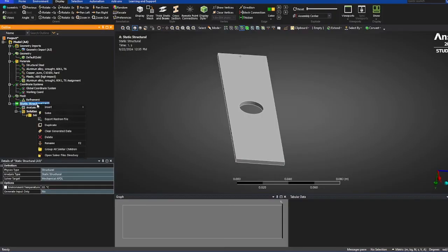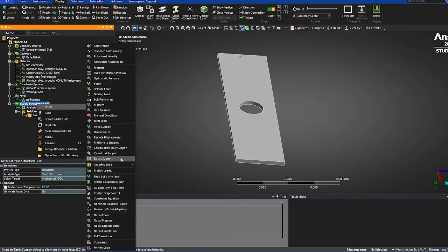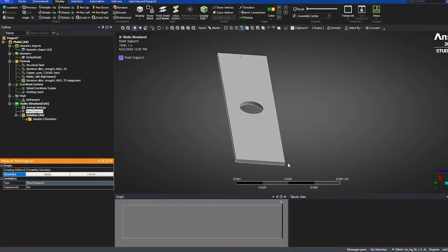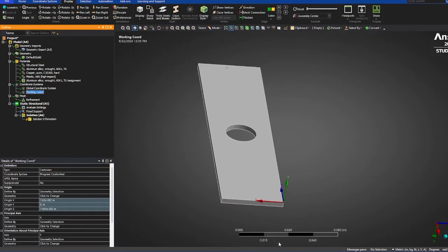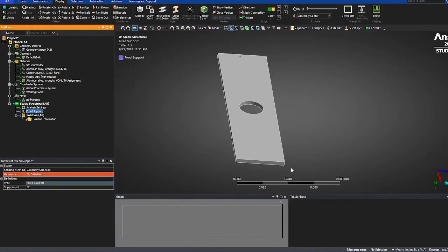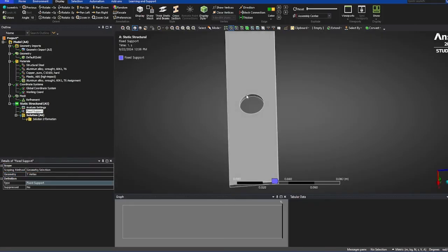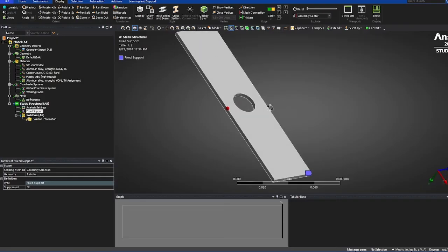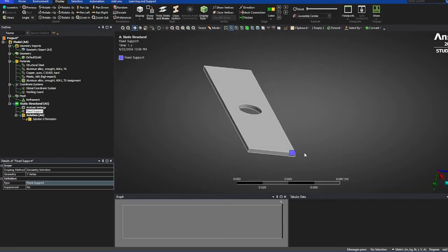Back in Ansys, I'm going to right-click, insert, and then add a fixed support. And so I just want to make sure that I'm choosing the location of my origin. So I'm just going to double check that real quick by actually clicking on the origin that I pre-set up. And that's right there. So I will go back, choose the point tool, and hit OK to set my new fixed location. So remember, in SolidWorks, this part would now be able to rotate around just that simple point.